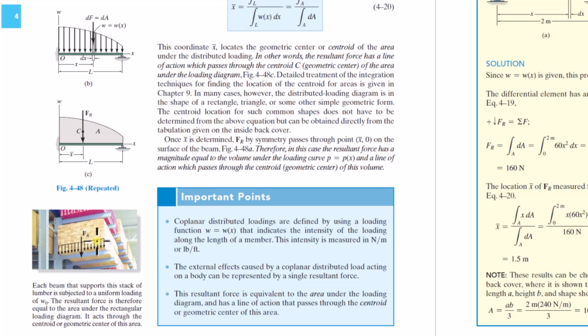But if it was a small piece, like a small heavy cylinder or something, then what we've been doing is that area of contact is small relative to the size of the structure, so you just put a concentrated force assumption there.